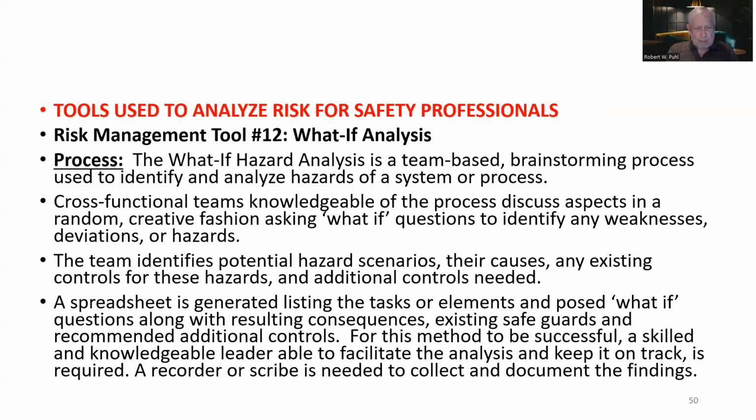A spreadsheet is generated listing the tasks or elements and posed what-if questions, along with the resulting consequences, existing safeguards, and recommended additional controls. For this method to be successful, a skilled and knowledgeable leader able to facilitate the analysis and keep it on track is required. A recorder or scribe is needed to collect and document the findings.